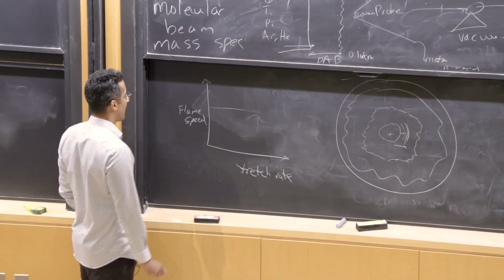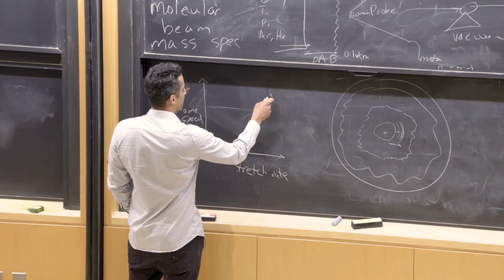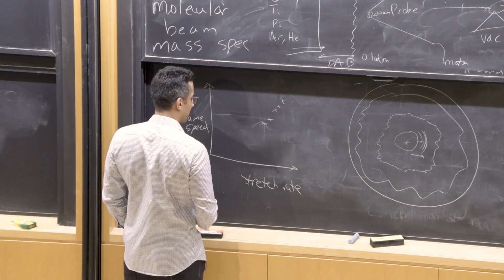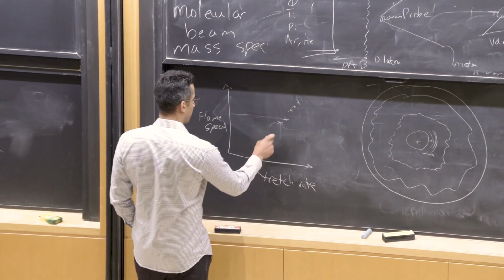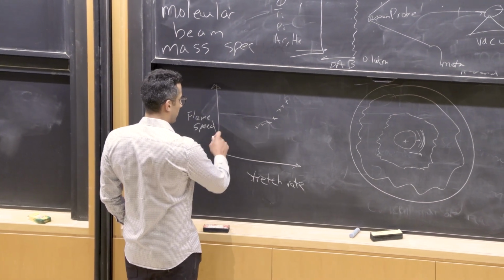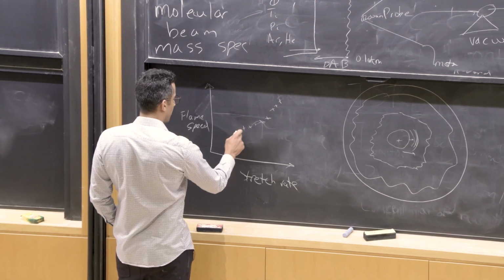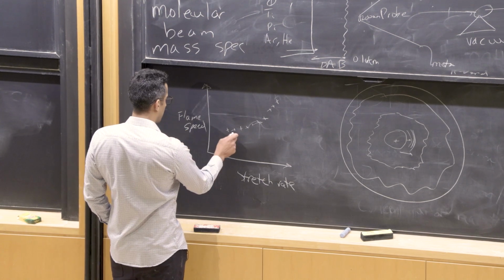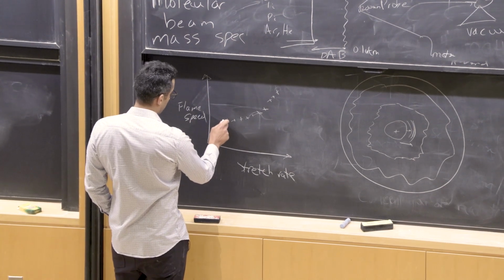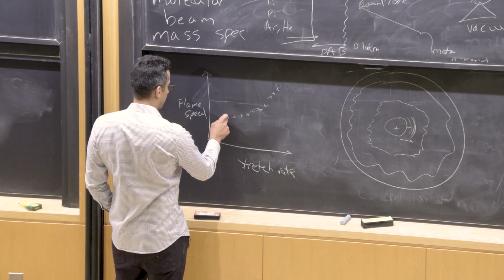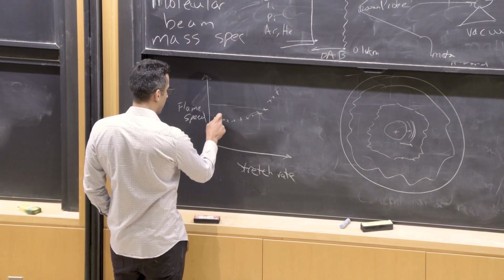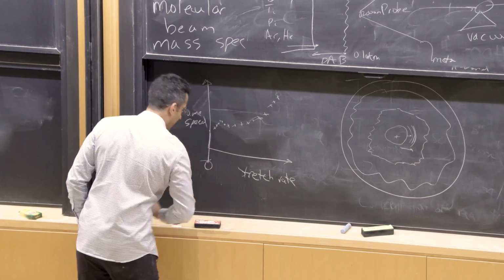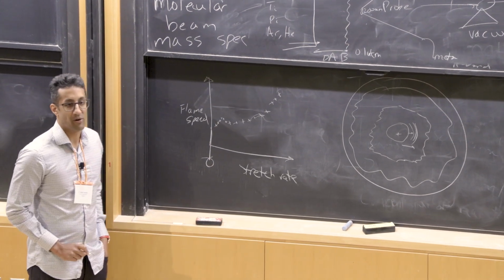And what happens is you have some flame speeds at high stretch. Okay, this is just pictorial. Don't take these plots as exact, okay? So what happens here is the flame speed increases as there's more stretch, but then as there's less stretch, the flame speed starts slowing down. Some people even show that sometimes at low stretch the flame speed goes up again, and then it comes down. And eventually, you're trying to get to this point of zero stretch, which is the point you can't measure,